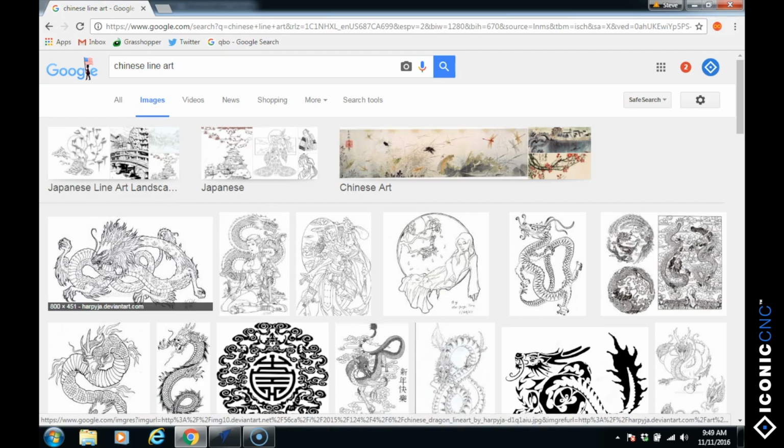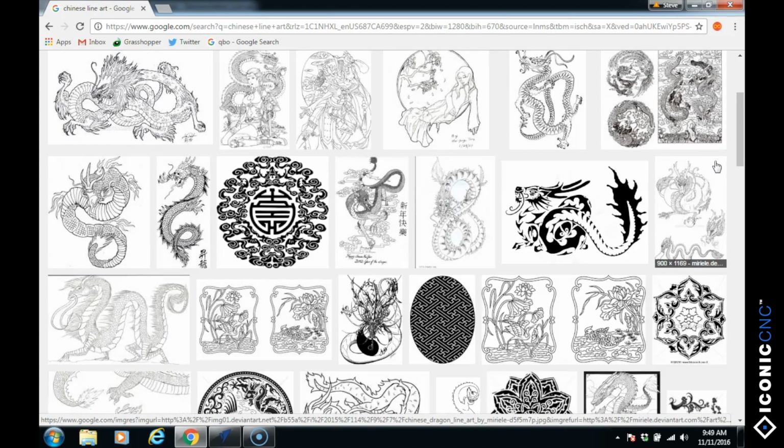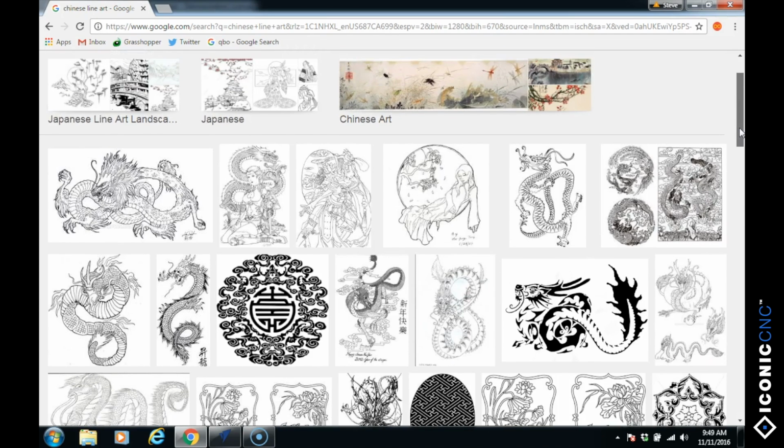The other issue that you have is, if we click in on this one as an example, you're looking at all these really fine lines. When you machine these, you'll literally be machining to 2 or 3 thousandths of an inch. If you don't have a piece of material that's absolutely flat, and anybody who's worked in woodworking for any length of time knows that there's no such thing as a flat piece of wood, then you're going to have some areas that over machine, some areas that under machine, and in fact some areas that may not machine at all, because at 2 or 3 thousandths of an inch tolerance for error, it just may not happen. So those are the three main criteria that you want to consider.